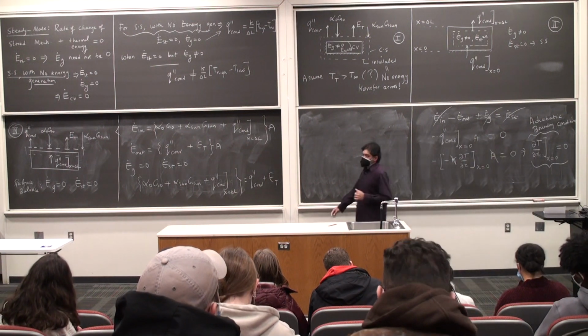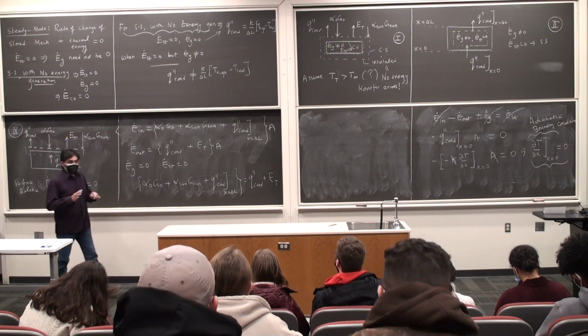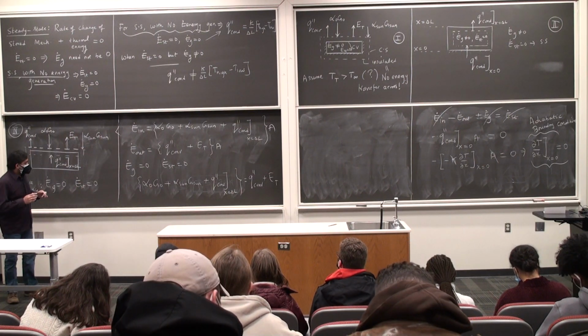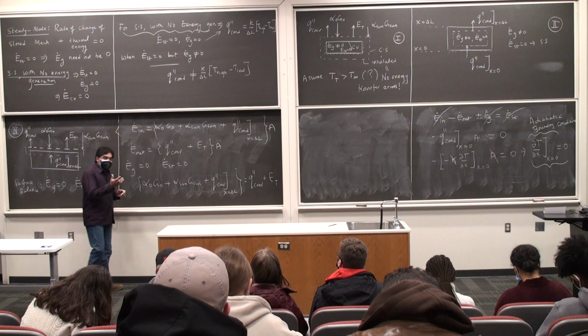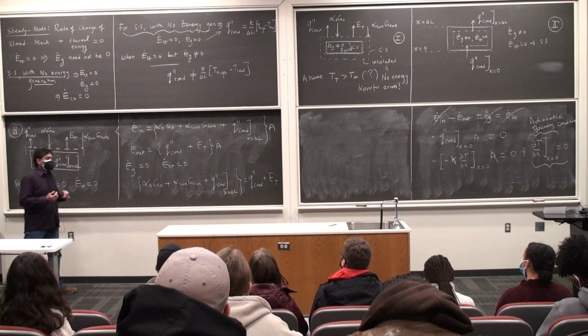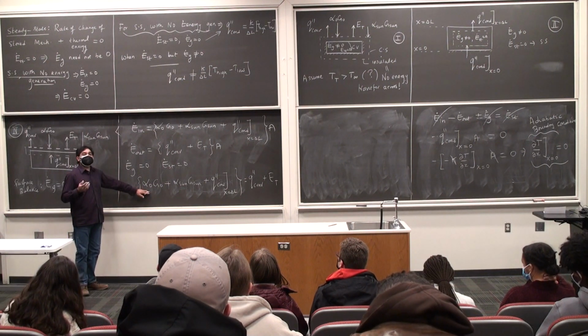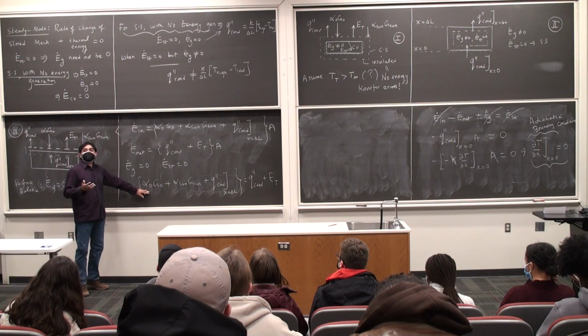We have a couple of options. We just did a lot of hard work, found out the temperature of the top surface, right? So if I need to find the conductive heat flux at the top surface, at x equal to delta L, at the boundary of the top surface, then I can use this particular equation here because I have all the answers known to me. So I can substitute and I can solve.